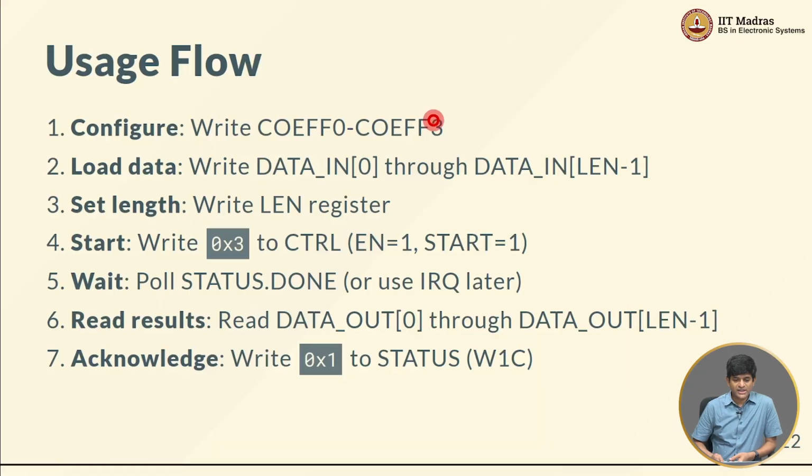Okay, so what we saw was how we could have this FIR filter with an AXI Lite interface, connect it up with a Renode emulation platform, and go through the process of testing out our device drivers, making sure that they actually work with the hardware that we have, which is modeled directly in RTL, and we don't need to have some other kind of dummy model just to work on our driver development, right. We can actually work against existing RTL code itself.